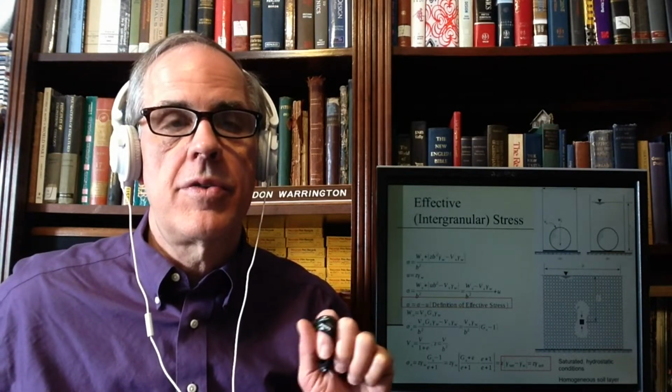And soils do not exhibit traditional, standard intergranular stress unless they're saturated. Non-saturated don't, because you've got air in the voids. It is equal to the saturated unit weight minus the unit weight of the water. You can also compute effective stresses by, instead of using total stresses minus pore water pressure, you can simply make them all saturated unit weights and compute just the old way, like you do total stresses.